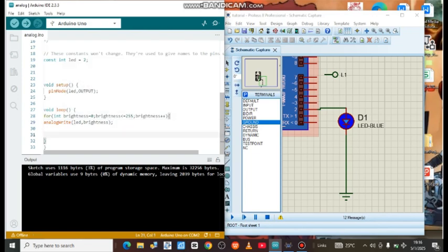Then it puts that same value into this analogWrite function, and this value is going to affect the LED pin. We want to put a delay here. My simulation is a bit slow, so I want it to play for a pretty short time. So every 10 milliseconds it goes through the loop, we assign a value to analogWrite, and that value increases each time it goes through.